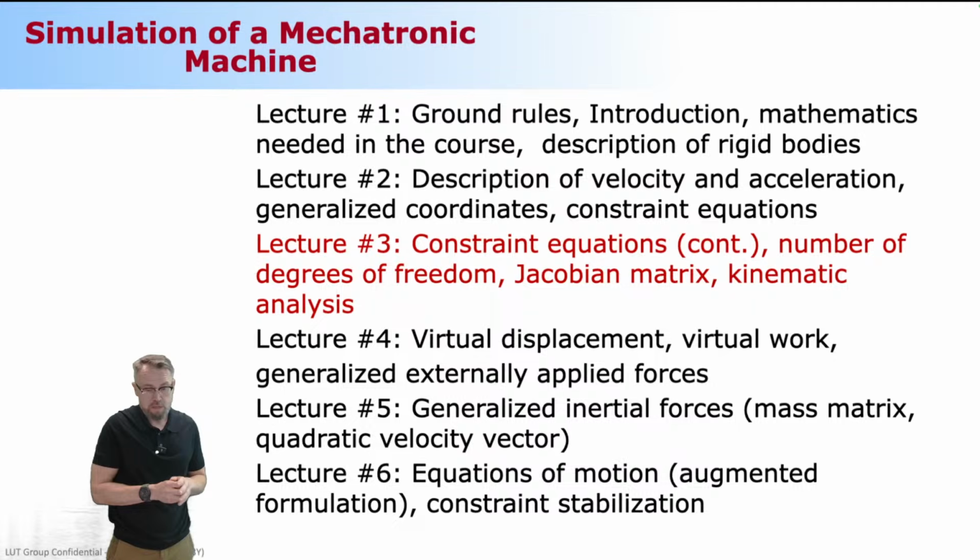And then what comes after that is that if everything goes like in the movies, which I doubt, we are able to close the case, which is called kinematic analysis. Remember, the kinematic analysis is all about the motion, it's the art of motion. It's not related to forces. Kinematics is not telling you anything about the forces because it's based on the constraints and motion. Basically, what I wanted to say is that it is based on constraints and driven constraints, the ones that are giving the motion and the other ones that are limiting the motion possibilities.